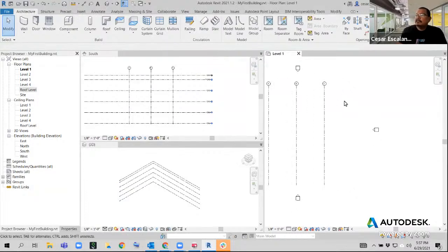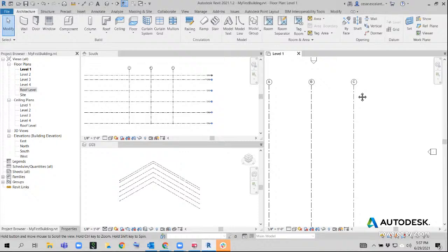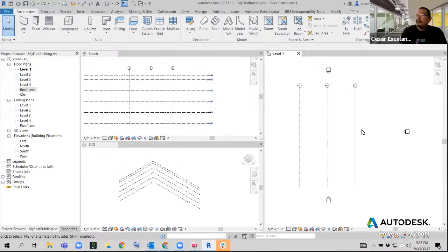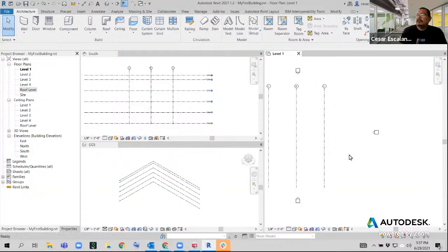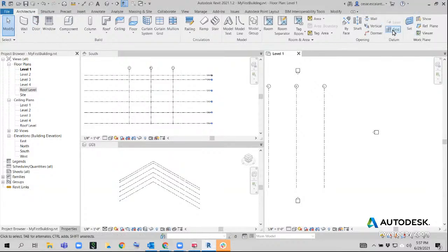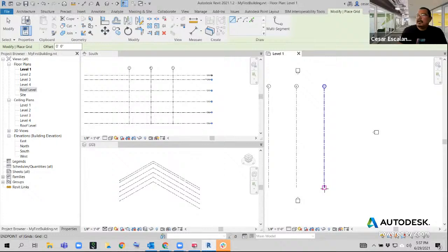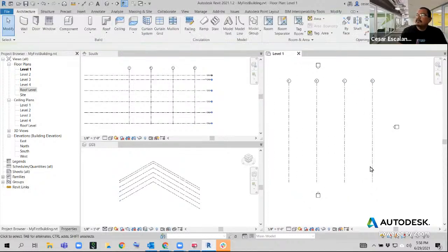Did that work, Dina? Can you repeat again? I just showed you how to create a new grid. So I'm going to do another one. Go to architecture grid, snap towards the bottom, move towards the right. And when you arrive to the 30 feet, that's your first click. And then when you snap to the extension above, that's your other click, and then escape.